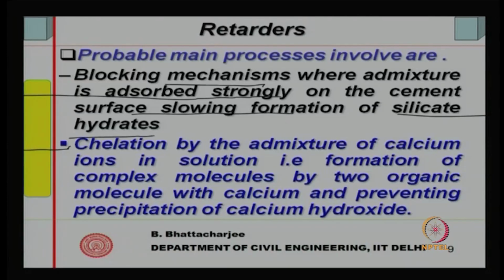So, the organic compounds in the retarder can form a complex with the calcium ion, and therefore prevent precipitation of calcium hydroxide. So, calcium hydroxide precipitation is prevented.